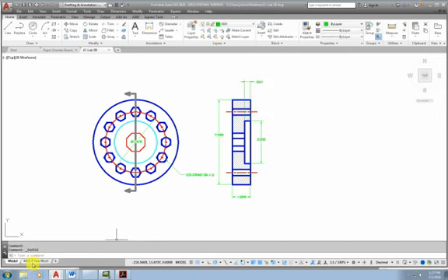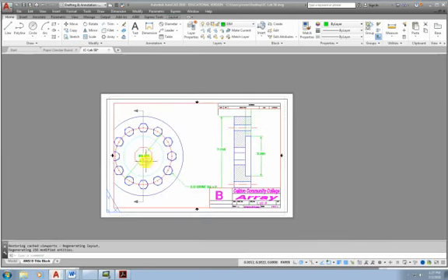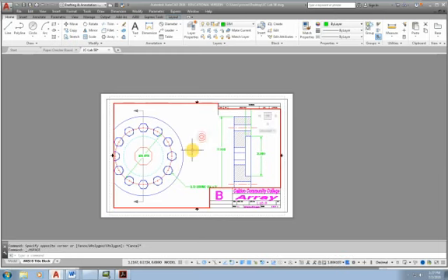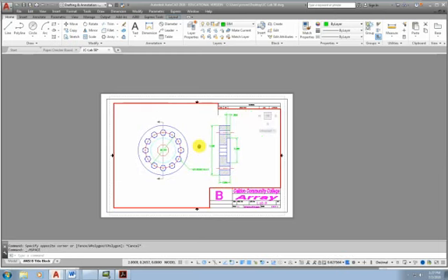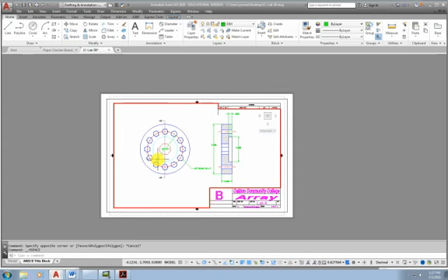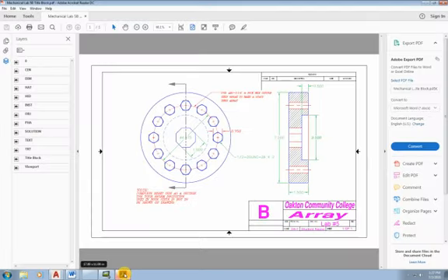Alright, click on the tab for the title block and you'll be changed over to what's called paper space. Double click in the viewport, and then if we turn the wheel on the mouse we can adjust the magnification level. If we look at the drawing we can see that the scale is 3/4 equals 1, 3/4 of an inch equals 1 inch, 0.75 equals 1.